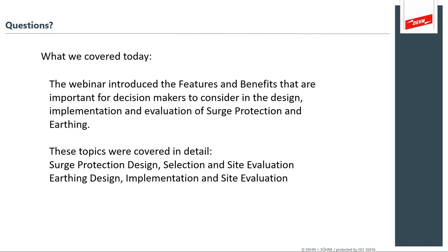Yeah, so in other words, if I can just say back what you're saying, the voltage protection level that a surge protection device provides for an installation is not just the rating across the SPD, but it includes the conductor that's run from the phase to the SPD and from the SPD to ground. That's the whole voltage protection level between line and ground that the equipment is going to see. So in other words, the sum of the voltage drop over the wire from phase to SPD, the voltage protection level of the SPD, as well as the voltage drop from the wire from the SPD to ground, that sum will basically be the final voltage that your equipment will see.